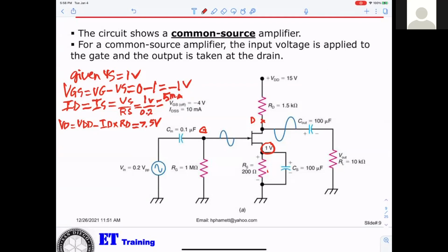And we're bypassing what? We're bypassing the 200 ohm. So what happens to the AC signal there? We don't have any AC at the... You're talking about the CS. Yeah, CS, they will be shorted to the ground. The AC gets shorted to the ground. Exactly. Okay, thank you. That is a bypass.